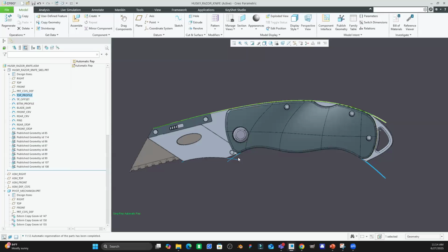So a lot of thinking has to go into place. A lot of people are like, oh, it takes time to set up this skeleton model. We don't really have that time. We just have to get started and start making these parts and then do the bottom-up assembly approach. That's understandable, but what happens is, if you don't use a skeleton model, and you have a larger assembly and everybody's working and then finally trying to assemble these things together, when you do have to go back and make mid to late stage changes to your assembly, there's a lot of rework that happens, right? This person has to adjust this assembly or this part to make it fit and this other part.